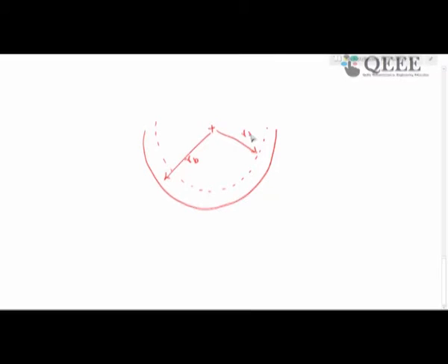So, let us be clear on this, that there is a base circle Rb. From the same center there is a dedendum circle which, just for the parameters that have been taken, happens to be lesser than Rb. So, we are talking about a situation where Rb is greater than Rd.